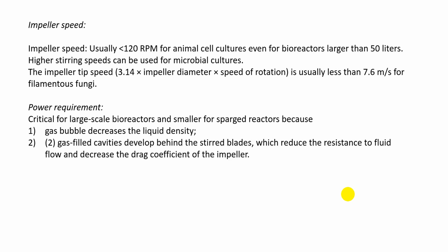It is critical for large scale bioreactors and smaller for sparged reactors, because the gas bubbles decrease the liquid density and the gas filled cavities develop behind the stirrer blades, which reduce the resistance to fluid flow and decrease the drag coefficient of the impeller.